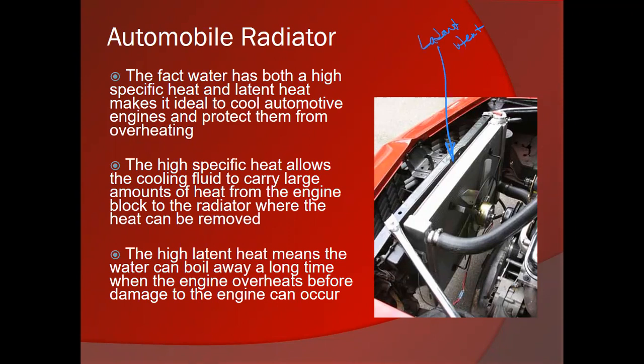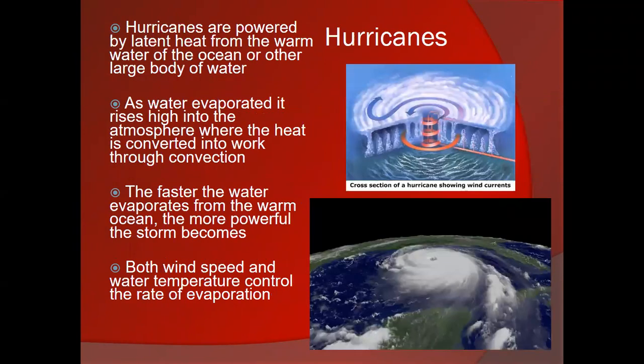So when you see your radiator boiling over, that's actually the water being converted into gas because your car can't get rid of the heat fast enough. And that's getting rid of the excess energy that could be damaging your engine. Of course, if you boil away all your coolant, you're going to be in a lot of trouble because that engine's either going to shut down or it's going to get damaged. So the newer engines do have protection. So again, latent heat is very important for this.